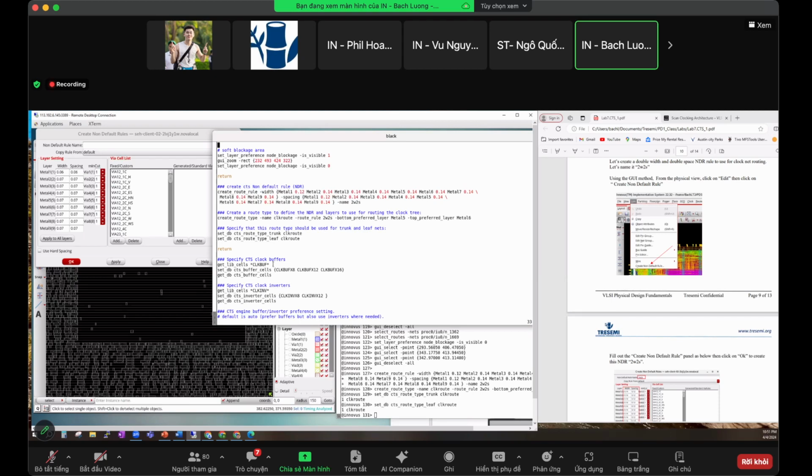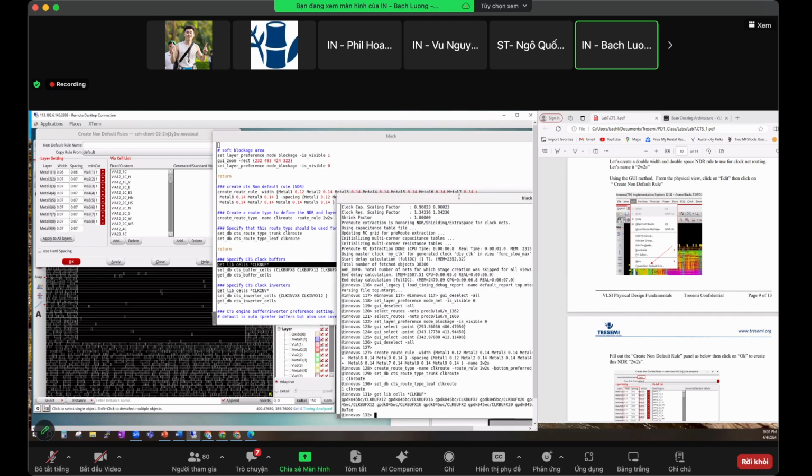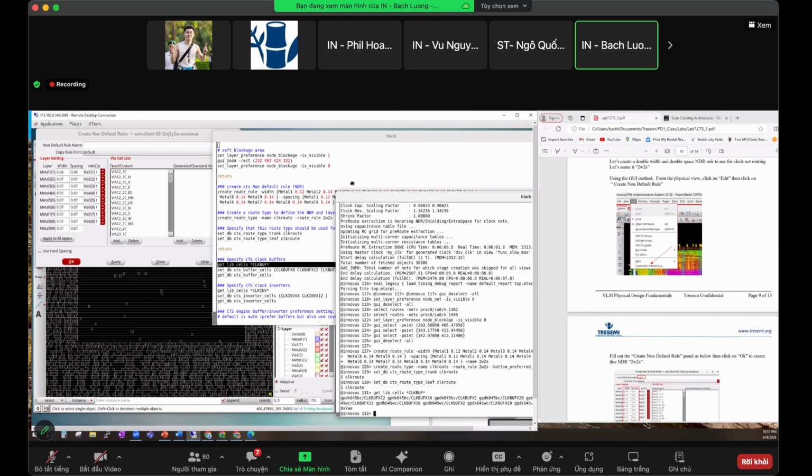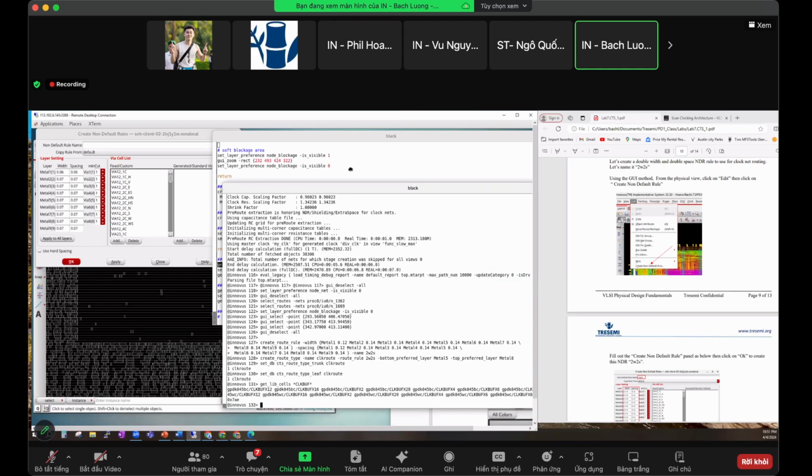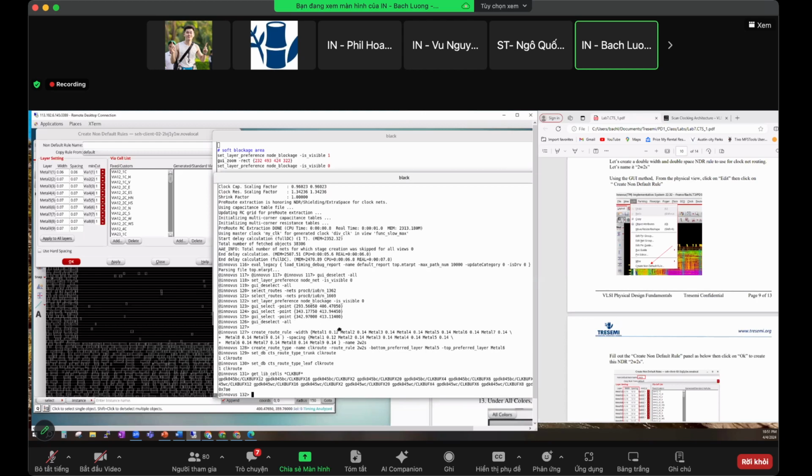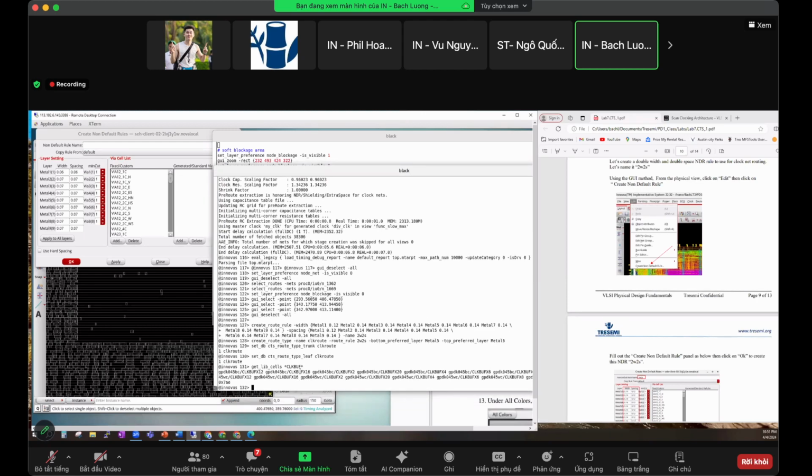Okay, and then here, this is the Tcl. So let's look at getting all the clock buffers in the libraries available. You can see. Let me move this over. So get lib cell clock buff, because I know usually a clock buffer will be named something like clock buff. So you can just grab the wildcard star, and it'll come up. So here clock 12, clock 16, X2, 20.